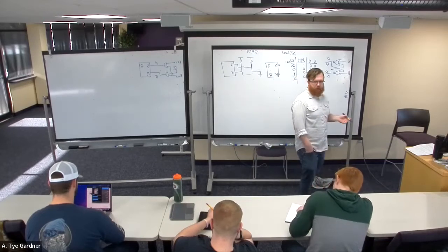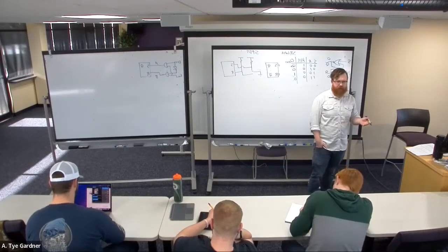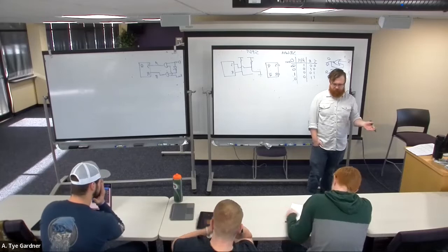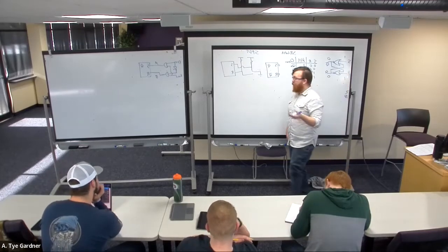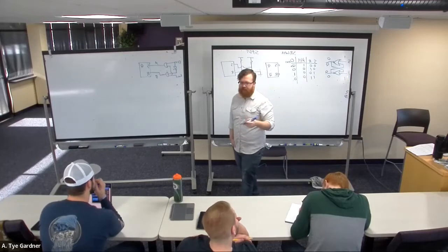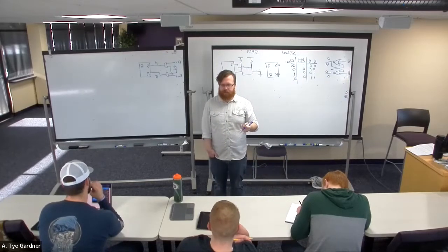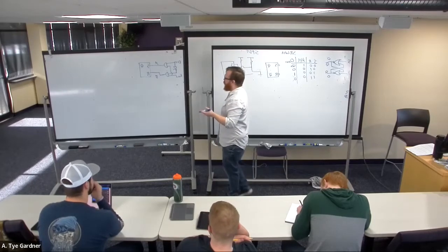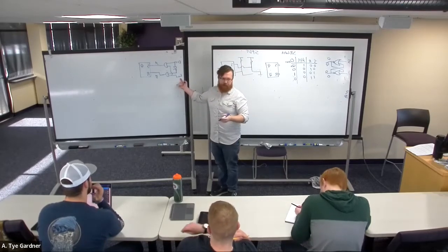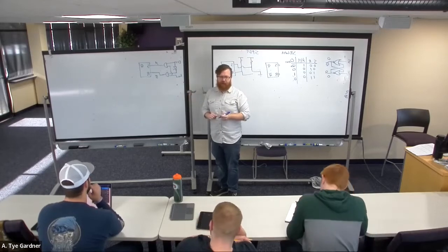If enable is 0, can A and B ever change? No, they're 0. If enable is off, they're both off. Meaning, I will never set or reset if enable is 0, which is nice. So that also means that if I'm not enabled, I am just remembering what my last value was.